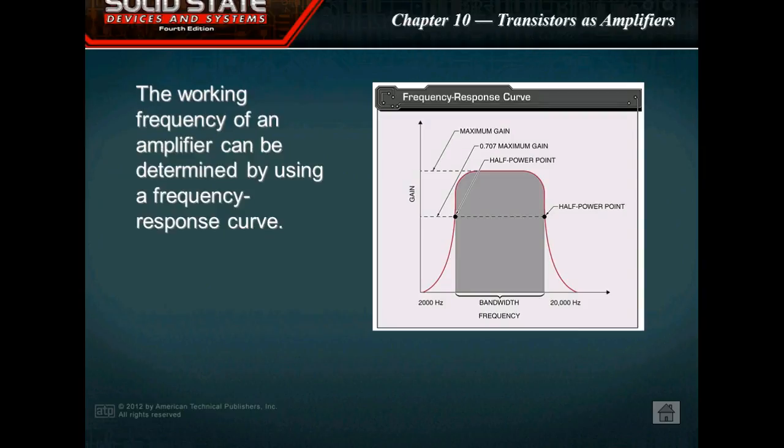We talked about bandwidth. Are you okay? So what is bandwidth? Well, it's actually a range that a medium can reliably pass, right? You understand? And the main part is the half power point, which occurs at 70.7% of the voltage, right?